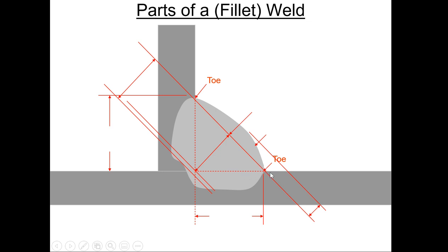Or can I see gaps in here? Can I see gaps that give us problems? And to think that the material doesn't have any fusion from the base metal. Again, TIG welding gives us so many advantages to seeing exactly what we see, but you have to recognize those to make it real. There's the face of the weld, the part you can see, looking for porosity and so forth. The theoretical throat is the size of this weld.